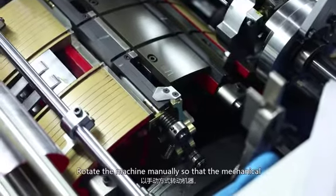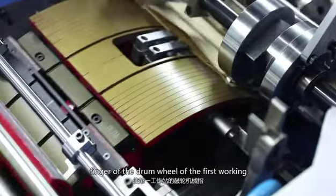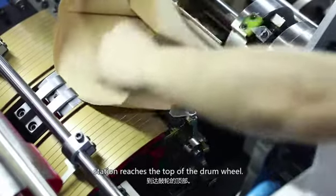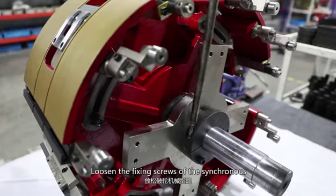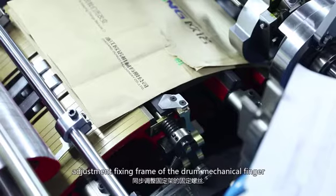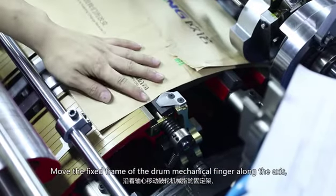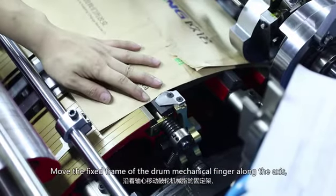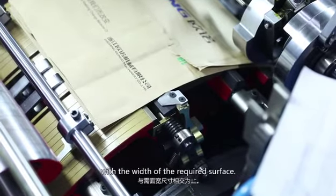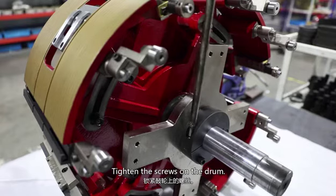Rotate the machine manually so that the mechanical finger of the drum wheel of the first working station reaches the top of the drum wheel. Loosen the fixing screws of the synchronous adjustment fixing frame of the drum mechanical finger. Move the fixed frame of the drum mechanical finger along the axis so that the drum mechanical fingertip intersects with the width of the required surface. Tighten the screws on the drum.